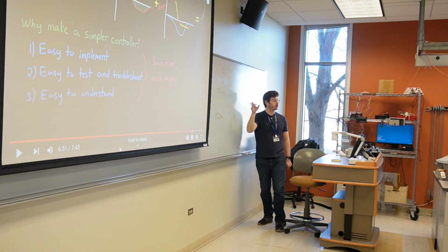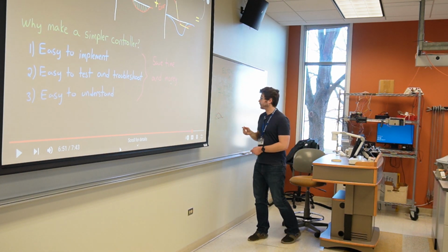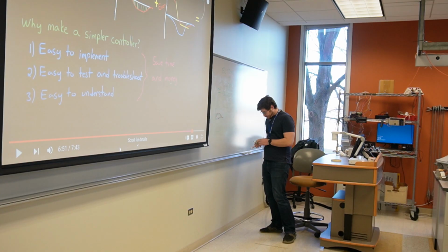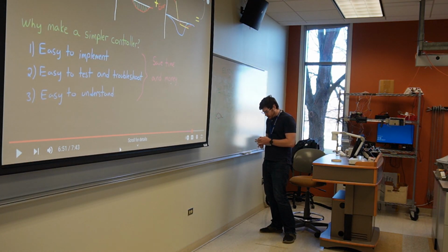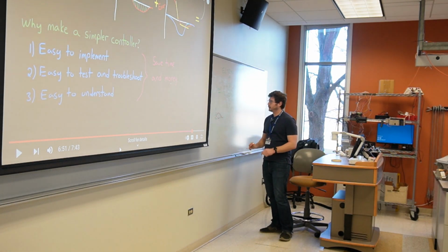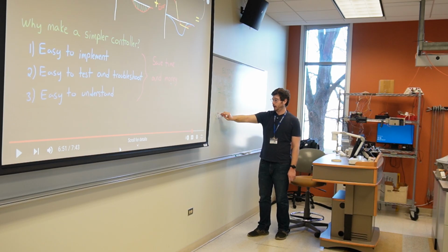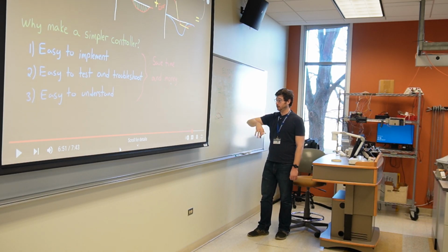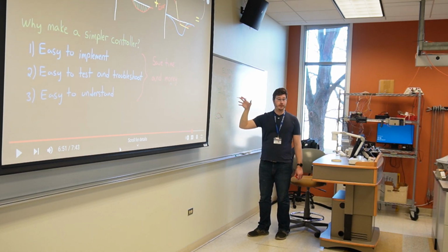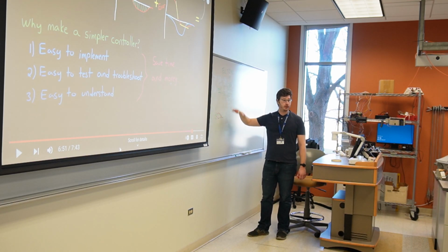That's what the I term does. It's really useful, okay? The D term is not often used. Like I said, most things can be accomplished with the P and I only. So P would, again, be set to anything between 0 and 100. Really, it doesn't have an upper bound. It's just how hard you want it to respond to things.